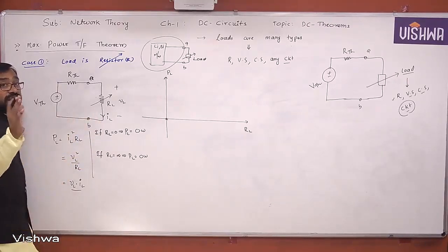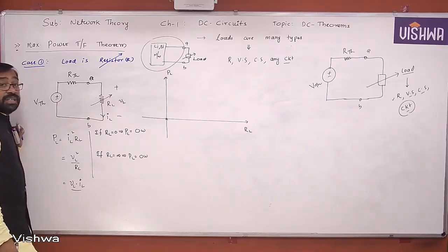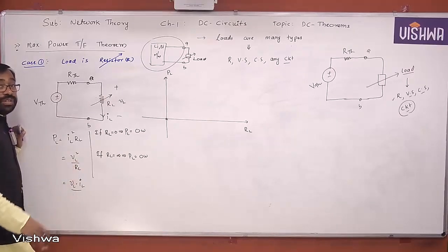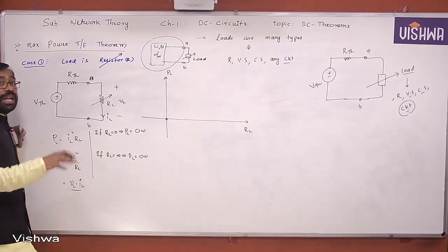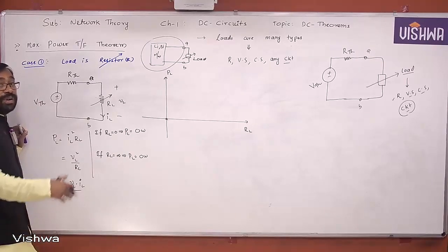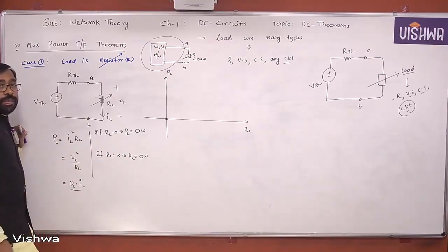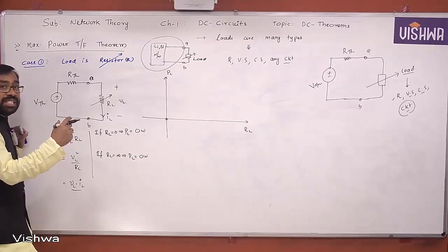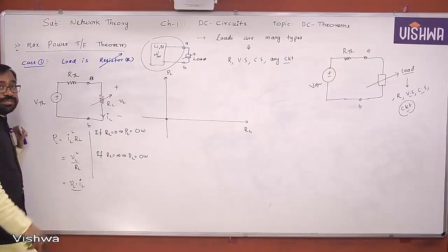I think you might have studied open circuit test and short circuit test in the case of transformer or DC machine. Most of the people, even EC or EEE or instrumentation, anybody will do the experiments in the laboratory. In the case of short circuit test, the load is shorted. So what is the power transfer to the load? 0 only. Whatever the wattmeter reading is observed in the laboratory, that is actually displaying the losses.